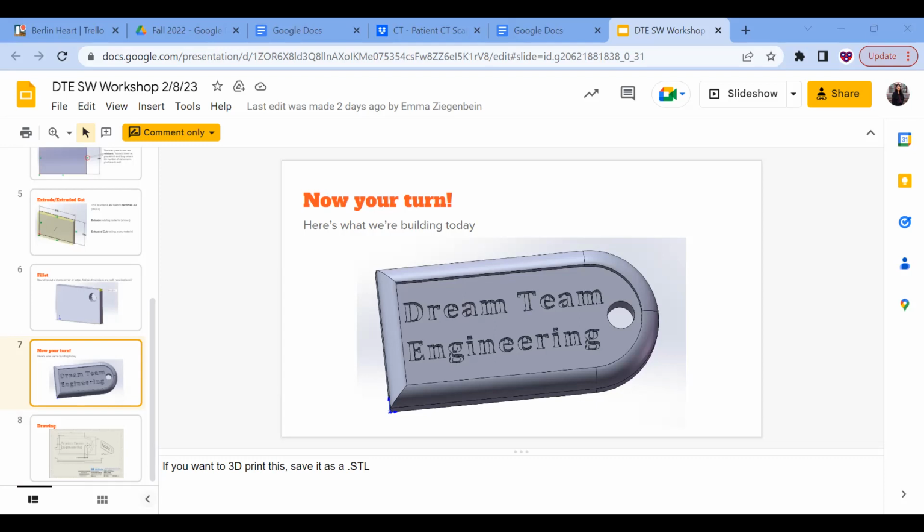But we're just going to go straight up, and then you'll again see the relation to make it vertical. And so you click, and so there's one line. SolidWorks will continue with the same feature that you have. So we're going to keep going, and we're going to make this line horizontal. And then I'm going to press escape to get out of that, and then L again.